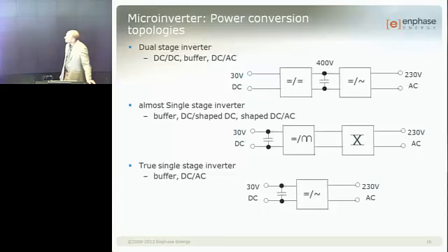This we're still using now, actually. This approach allows a much higher efficiency than the previous one, because on the first block diagram, you process energy twice in a fairly intensive way. So the booster has losses, the inverter has losses, and they're both about the same. And if you get 97% on the first stage, you're really good. If you get 97% on the second stage, you're really good. So you end up at 94%, 95% range, conversion efficiency-wise.